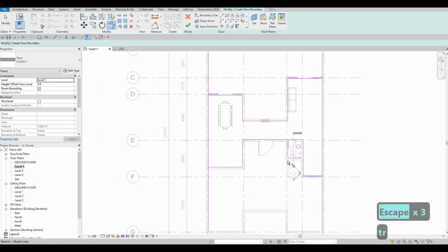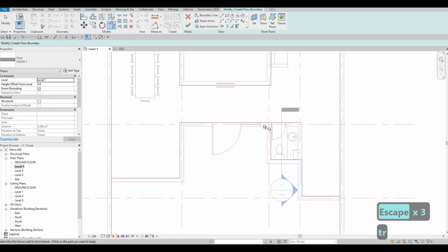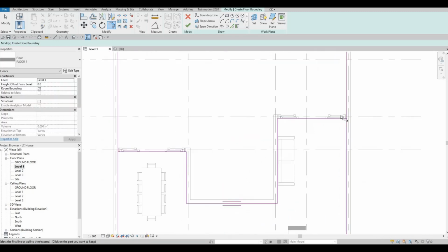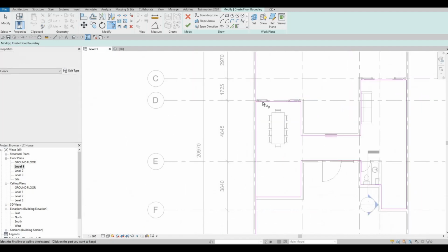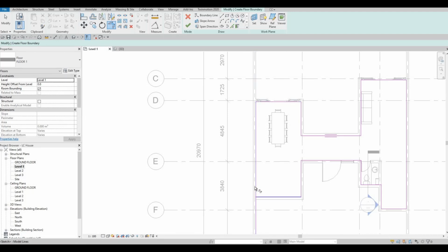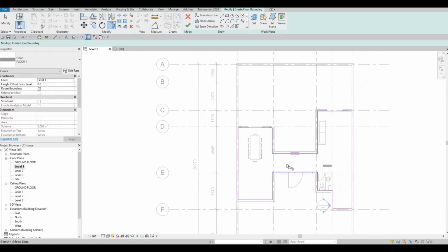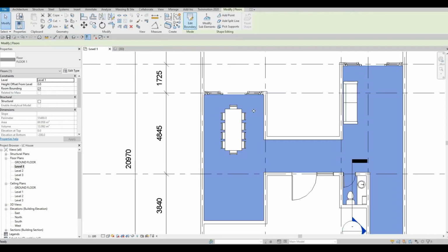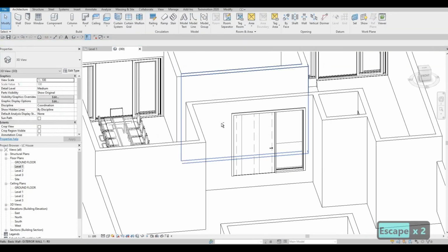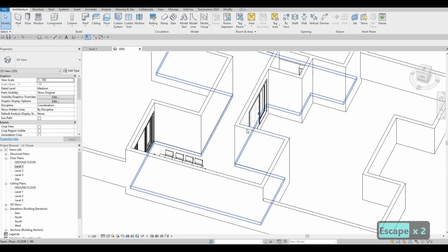So now TR, that's trim and extend. So go to all the corners and make sure that you trim and extend that. So it's like fillet in CAD, and it's just basically cleaning every corner up. Everything is selected. Everything is not overlapping. Once you do, you just need to click finish. If there's an error, you forgot something, or something is overlapped, it will let you know. So right now we did it perfectly. We have the floor right now.